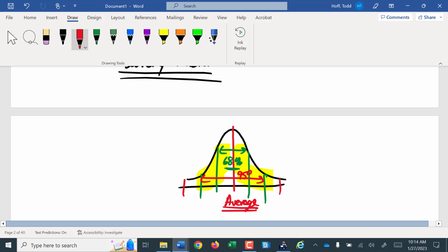And you can keep going. At 3 standard deviations, it's 99.7%, which means pretty much all of the ropes that we use are within 3 standard deviations of that average. But again, we're not going to go through the trouble of calculating that. Part of what the safety factor is doing is accounting for that variation in the ropes. So even though it says it's rated at 20,800 pounds, there might be some perfectly undamaged ropes that might only support 18,000 pounds, and others that might support 24,000 pounds just fine. So we're accounting for that variation with our safety factor.